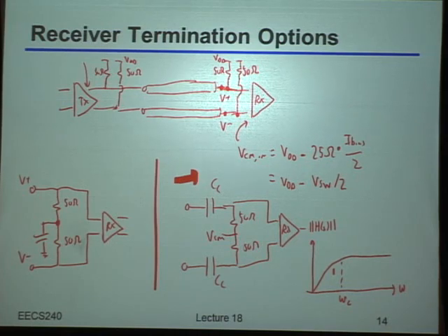On the other hand, indeed, if you want to be able to use this kind of trick, which again is quite common, what you'd basically do is you have to specify, well, what's the longest number of either repeated ones or repeated zeros you can get, and make sure that this corner frequency is sufficiently low in comparison to that. Make sense, everybody? Or? Yes?